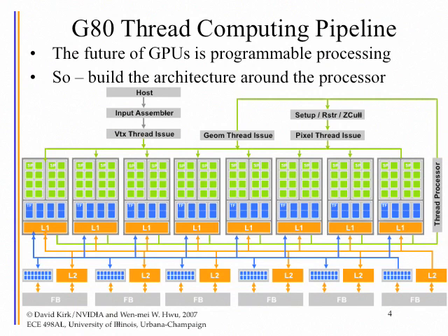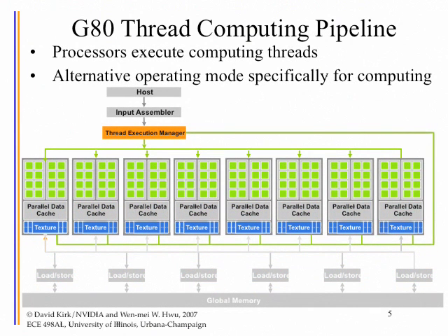So you may as well create another set of hardware interface which does not deal with vertex processing, and it doesn't generate threads on behalf of these commands. Right? This goes back to who generates the threads. So the programmer actually generates threads through the kernel invocation, and then the threads will just be issued by this simple piece of hardware into all the execution units. So this is a separate hardware interface that gets turned on when you switch mode. And that is the execution base of the CUDA programs.